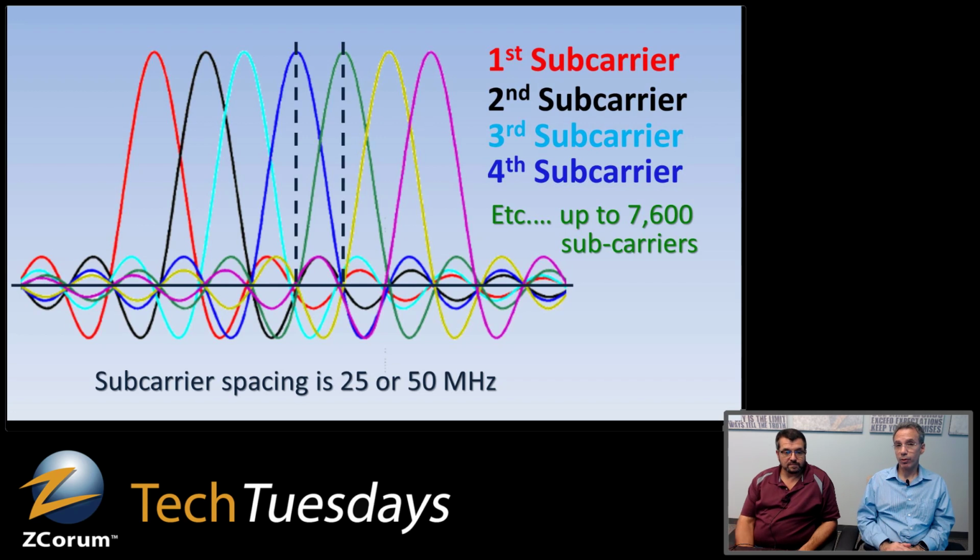Yeah, that's a good point, because you could start with OFDM and you don't have to deploy OFDMA right away, just like a lot of operators started with bonding just on the downstream and then later added upstream bonding. Yeah, most of the draw is on the downstream side to start with. But like I said, there's a lot of advantages to doing that. There's spectral efficiency. One of the interesting things about OFDM is you can have multiple profiles. That's something that we didn't cover here, so maybe we'll get into that next week, what to look for.